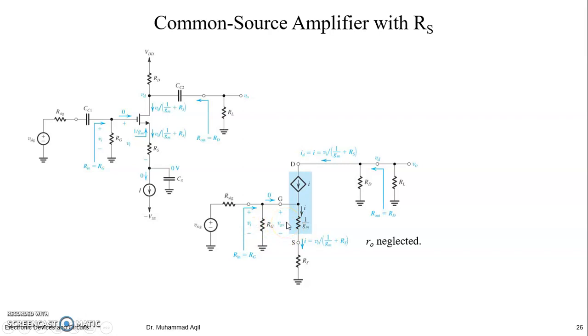Okay, and then you have this thing. Now you are having the GM VGS relation here. If you want to put VGS, take here, right? VGS is 1 upon GM divided by 1 upon GM plus RS, whole multiplied by VI. So you can bring VI here, put it down, find AV, and then again if you want to calculate the GV, you replace VGS with its formula with the VI, replace VI again with its formula with V signal, right? And then find the GV.